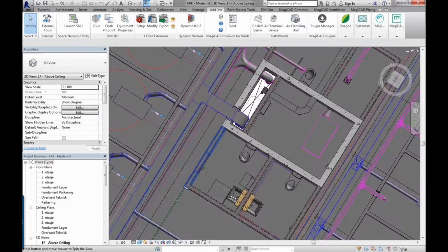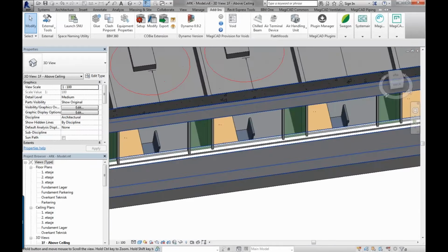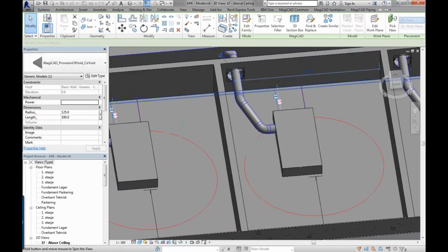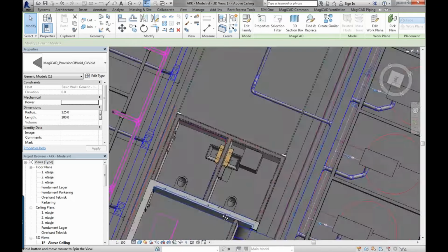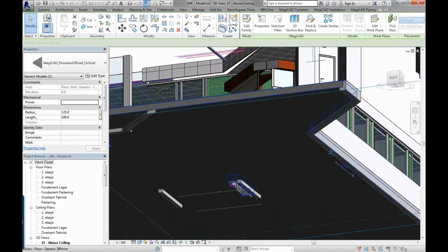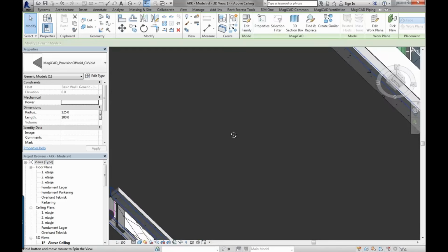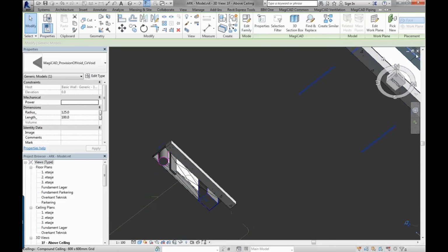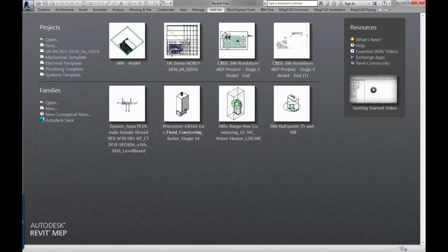and you can see what's happened now is it's actually cut the holes where we've requested it. So in the architectural model, they can now review. You can see it's actually cut a hole in the wall, so that's quite nice. So you can see exactly where your services and architecture are coordinated. You can see underneath the wall that it's now got the riser hole cut through there. So I'll just make these changes and save them, and then go back into the MEP model.